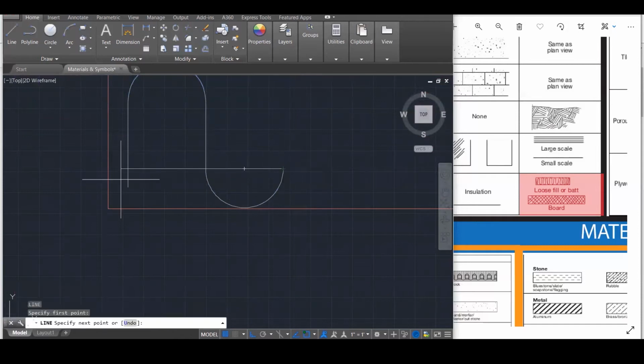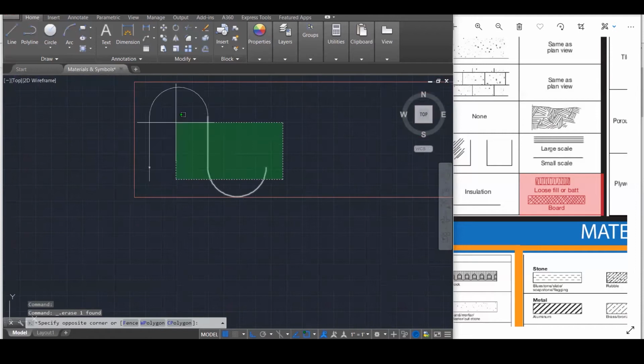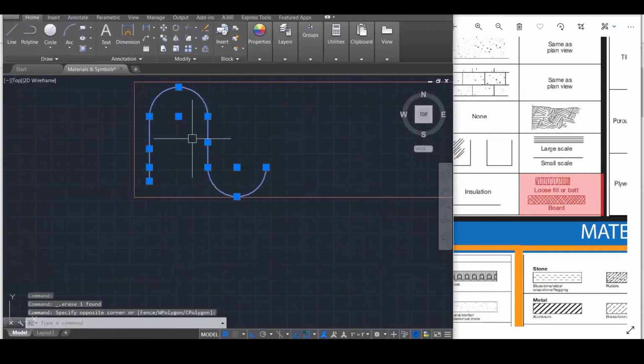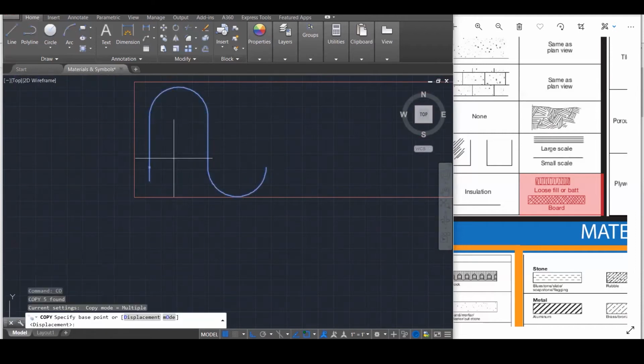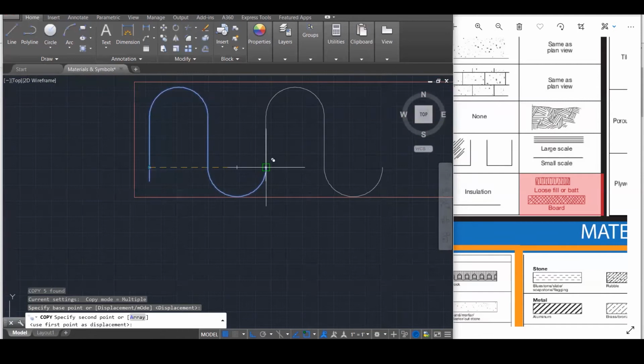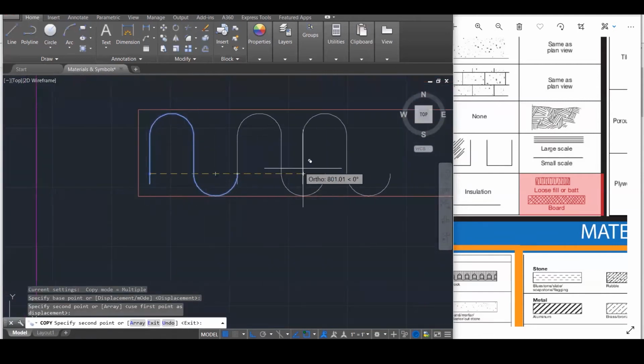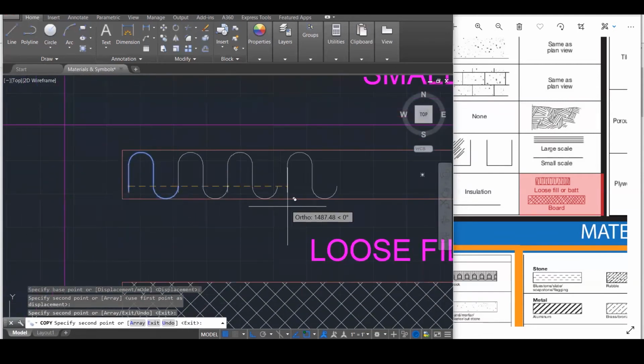I know what I gotta do. I gotta put a point here. So cool. So I want to grab it from that location. CO to copy. And to place a point there, you type POIN, and that brings up the point menu. All right. I think, are we doing it correctly? That goes up, comes down. Yeah.